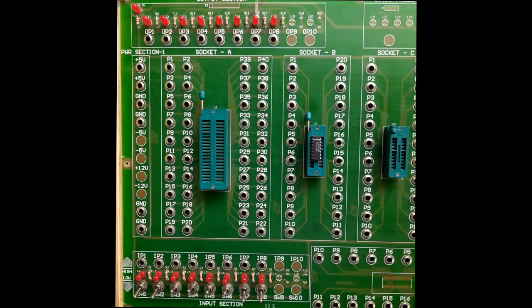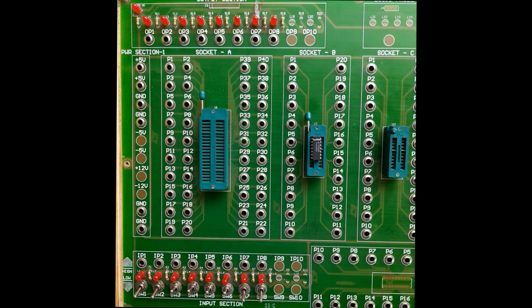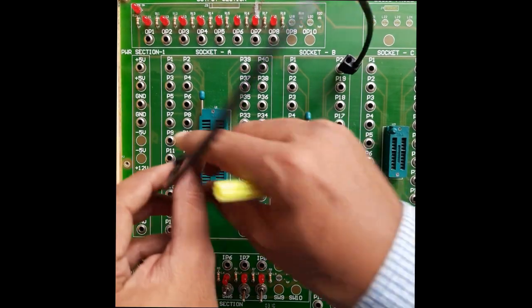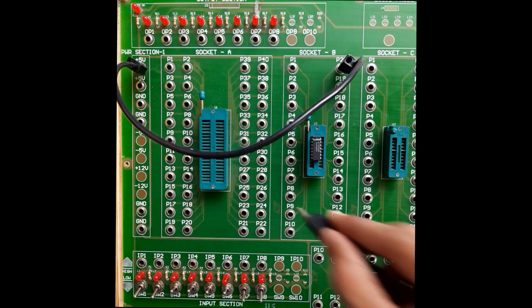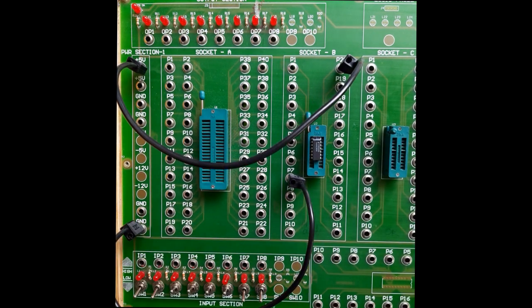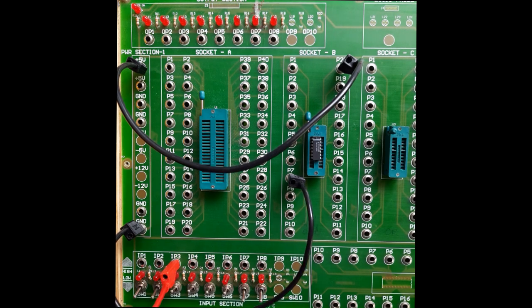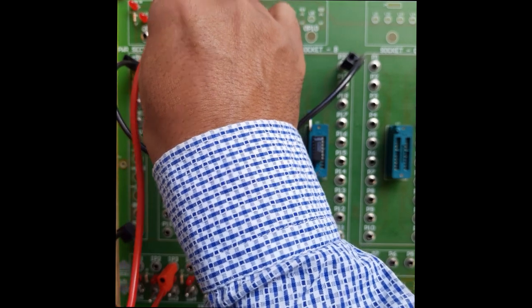So here I have considered the same IC 7486. The first step is the same: you have to connect the ground and the VCC. So first connect VCC. This is my VCC. Then at pin number 7 connect the ground. Then as per the circuit diagram, B3 is equal to G3. So I am considering this as G3, the input, and this is my output B3.